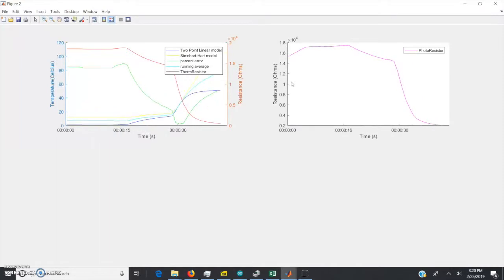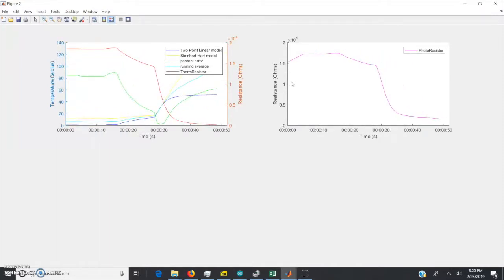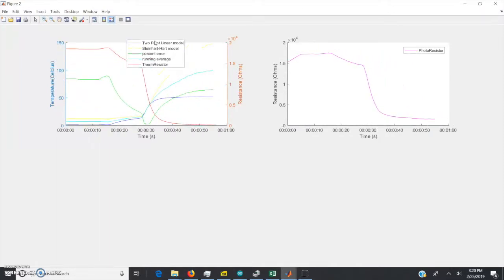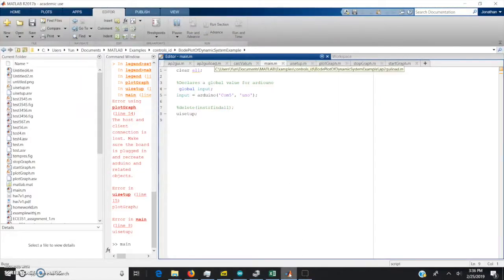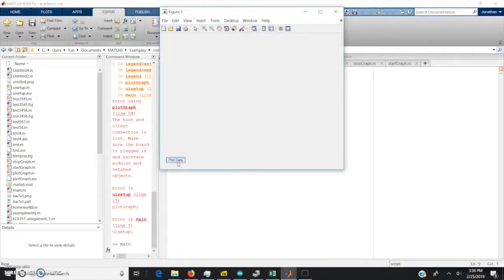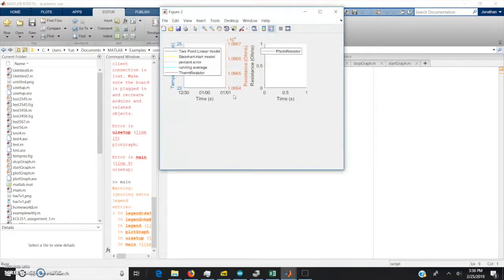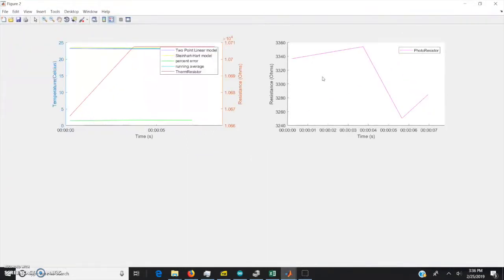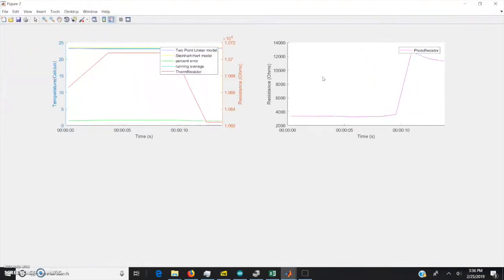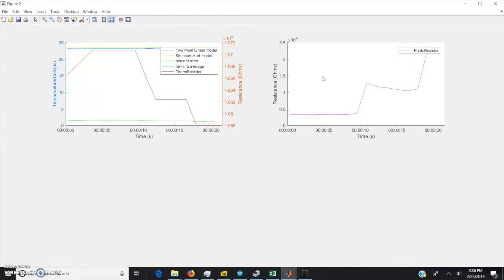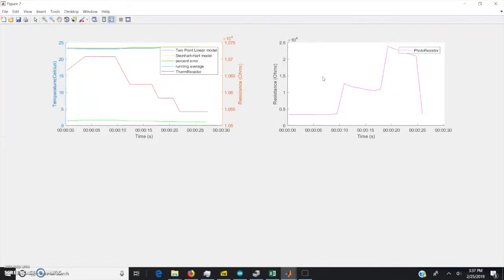And you can see the other statistics that changed with respect to the temperature applied. Now we begin to test the photocell data that we collect from the voltage divider circuit, and you can see that on the right hand graph that is about to show up, you can see the resistance change and go from high resistance to low resistance depending on whether it's in a light environment or in a very dark environment with no light.